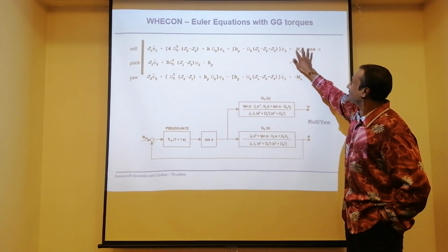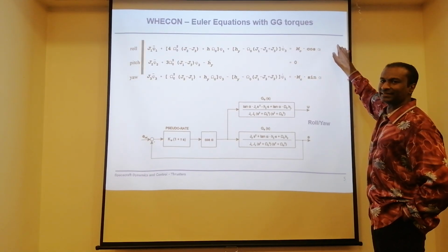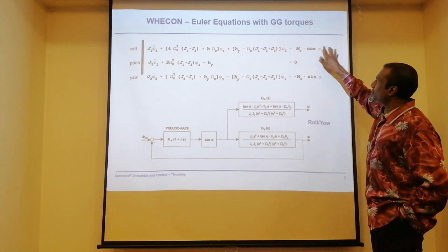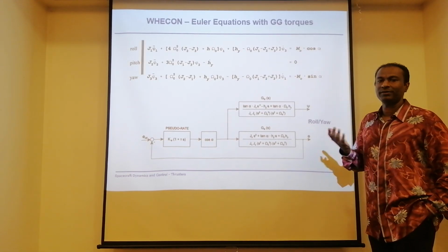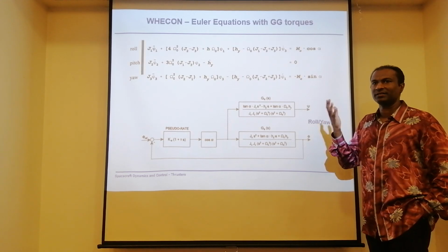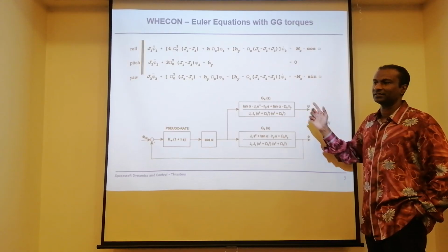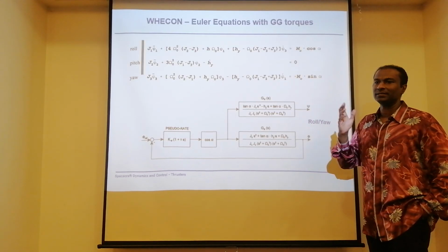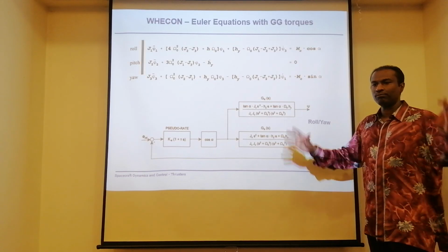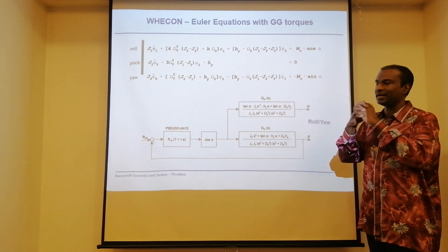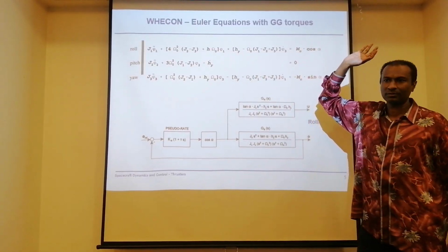Okay, let's say this is plus. There should be minus external disturbance torque. And let's say there is a minus 0.5 Newton meter external disturbance torque. I should give, that means the thruster should provide me plus 0.5 Newton meter torque. So both will be a net zero. When there is a net zero, nothing will disturb the satellite. That's what it says. Okay?